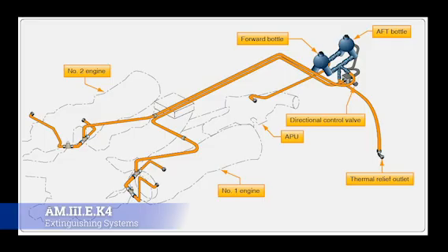Now, this could be a bunch of different types of fire extinguishing agents. Halon 1301 is one of them, but there are other ones out there as well. Some of them are very corrosive, so if you discharge the fire bottle, you're basically canning the engine no matter what.